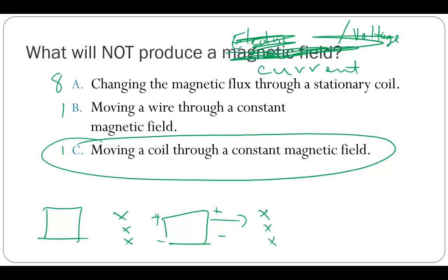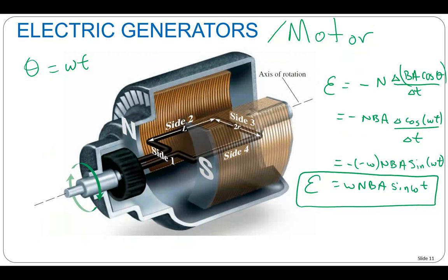Well, we were only talking about the generator aspect. Remember, a motor and a generator are the same design fundamentally. A motor is generally optimized for one purpose and a generator for the other, so they're not optimized to work equally, but they will both do the same thing. In fact, my understanding is that early automobiles had a generator and you started the car with a hand crank. Then some genius said, wait a minute, we have a generator, that's an electric motor. So you would use a battery and put current through the generator and connect it to the engine to start it. After that, you use it to charge the battery as a generator.